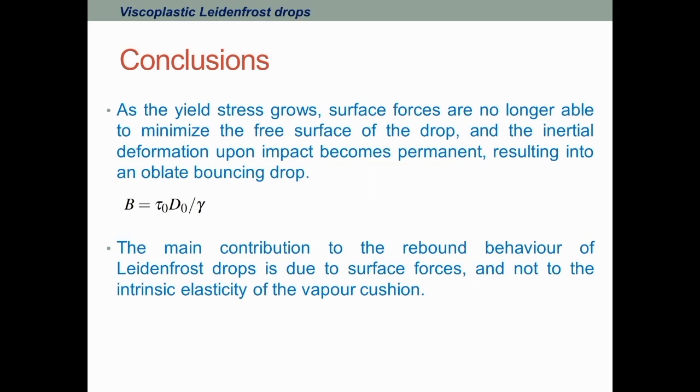resulting in an oblate bouncing drop. This can be expressed by the Bingham capillary number, which is a combination of the yield stress and the Laplace pressure. Also, the main contribution to the rebound behavior of Leidenfrost drops is due to the surface forces rather than the intrinsic elasticity of the vapor cushion.